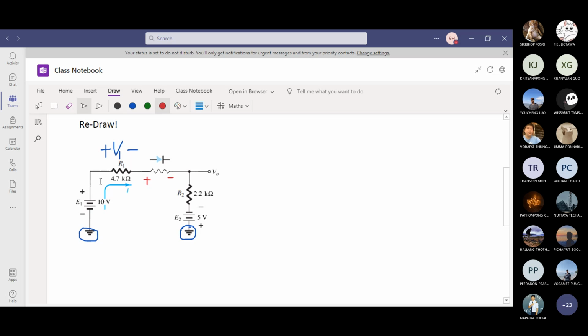At this point, the voltage on the anode side is 10 volt minus V1, whatever that is, but it definitely looks like a positive voltage, much larger than 0.7. On the negative side, there is a negative polarity joined with the negative side. It is fair to assume that this is negative, this is positive, so the diode is now forward biased, it is on.